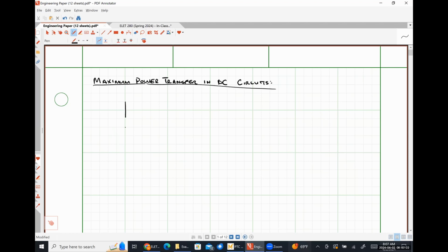So let's say that I had a DC circuit that I could represent by its Thevenin equivalent circuit. You guys remember what a Thevenin equivalent circuit is? Mildly. Okay. So in a Thevenin equivalent circuit, you've effectively condensed down your circuit into an electrically equivalent circuit that contains only a Thevenin voltage source in series with a Thevenin resistance.